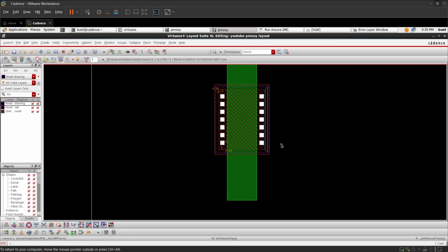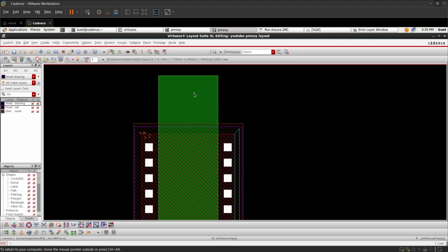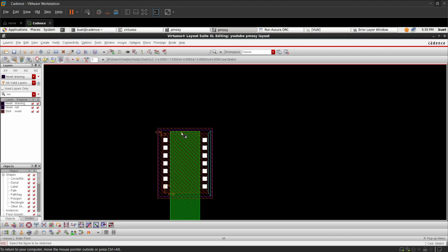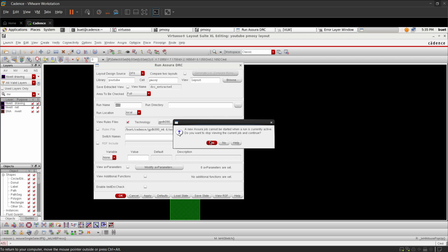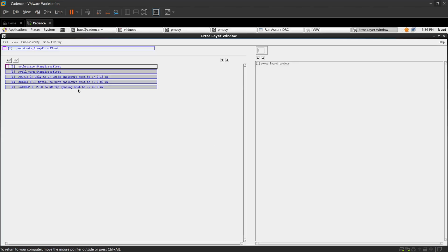Yeah, it's done. Next thing, you are supposed to see what should be the spacing between your poly edge and your oxide. Stretch this poly edge with respect to oxide. We'll be looking into it. Just save and run our DRC. Apply. See, as you can see, as we keep on resolving, the errors are disappearing, right? It means this is a way to approach any layout from scratch.